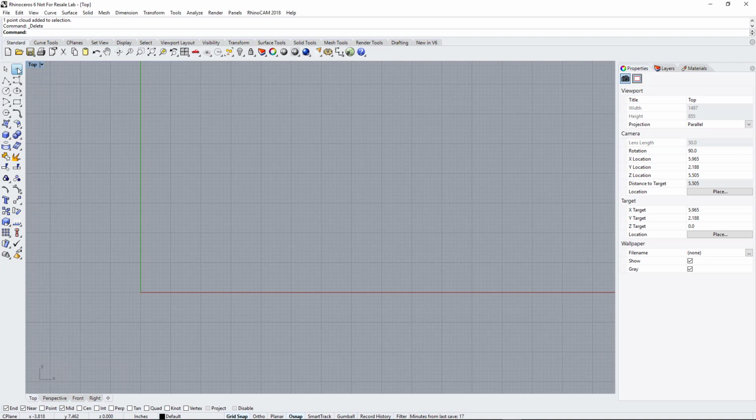So mainly for dropping points, we're going to be using the single point, multiple point, and possibly divide curve by length. So we'll talk about those three. So the first one is single point. By clicking on single point, it allows me to just drop a single point. Simple as that. I can type a location for the point right here, or I can just click on it.